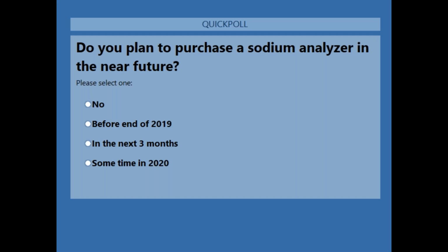Okay, so David wrote us a question regarding calibration. I think in our slide, Randy, we showed calibration at 200 and 2000 ppb. David is calibrating at 100 and 1000, but their samples are generally less than 0.5 ppb, excuse me, and they have an action limit of 2 ppb. Would there be any benefit from David using some different calibration standards, perhaps a 10 ppb and 100 ppb?